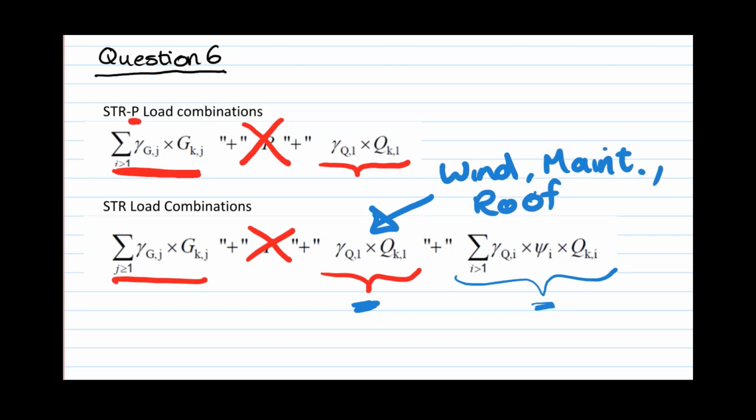We don't know, so we're going to generate a bunch of different combinations, test them, and see which gives us the worst bending moment, axial load or reaction, and use the worst case one to design. We might even find that the worst axial load in the column is from one combination, the worst beam design is from another, and the worst foundations from another. We're going to test all of them, and then depending on what we're designing, we'll pick the worst, but any could govern. And then we will just keep rotating through.